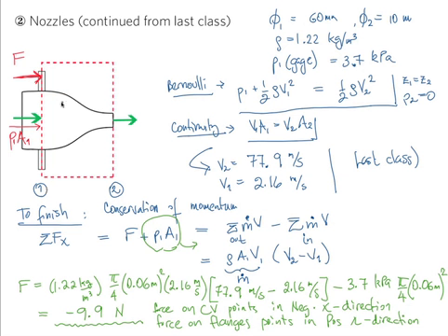This is the equation that we have applied here, right? Sum of forces on the control volume equals the change in momentum across this control volume. So we have pressure acting. We've drawn a volume that is this magic black box. And we've applied the equation of conservation of momentum for that box.